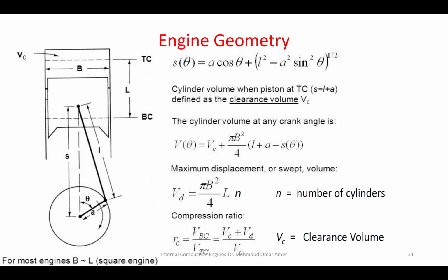What about those equations, the S of theta and the V of theta? You are not required to memorize these equations. They are just for your knowledge, especially if you are doing some research work or some simulations. As the piston moves, this distance changes as well as the volume above the piston. The volume above the piston changes from VD plus VC to VC.